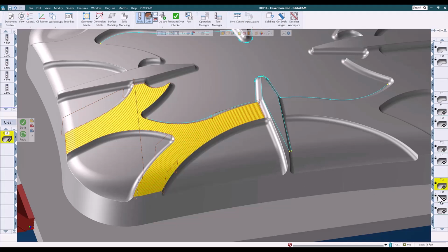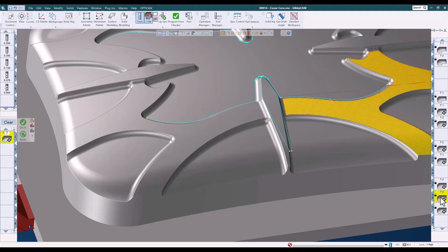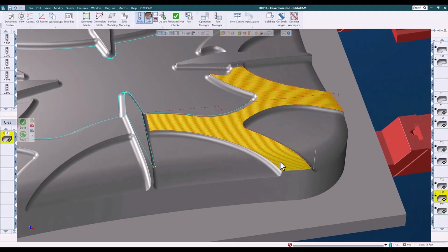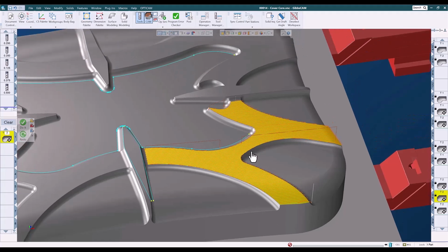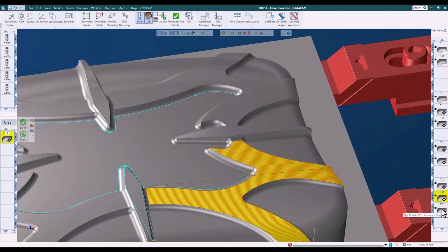This one is using a basic raster lace cut, but from the advanced 3D process. So it's still that linear stroke toolpath, but this is from the advanced 3D. It has very few retracts, but really it doesn't flow very well with this shape. The shape's not straight, so a straight line toolpath is not really going to flow with it.